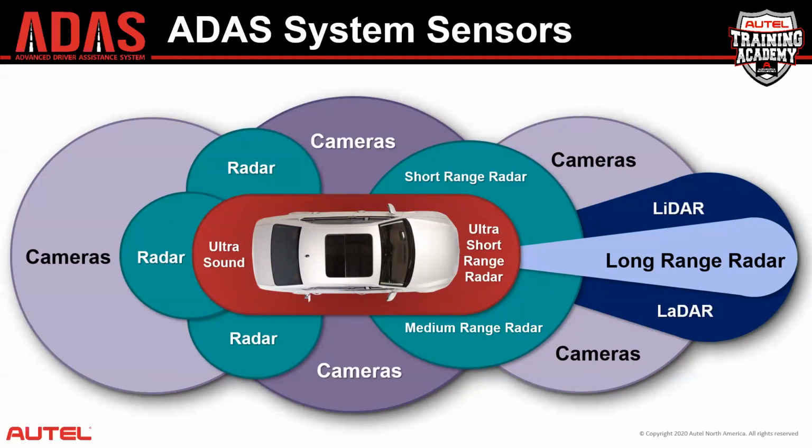The camera and the long-range radar work together to detect objects on the road, whether they're within a few meters of the vehicle or maybe 100 meters in front of the vehicle. This fusion of sensors working together, it's actually called sensor fusion, allows the vehicle engineers to develop more and more advanced ADAS systems by allowing multiple components or existing components to perform other functions.